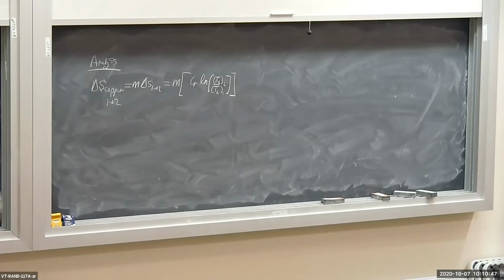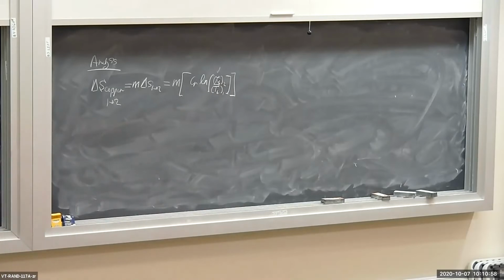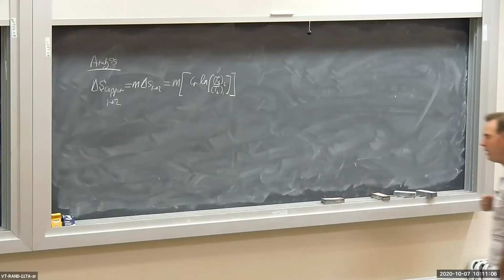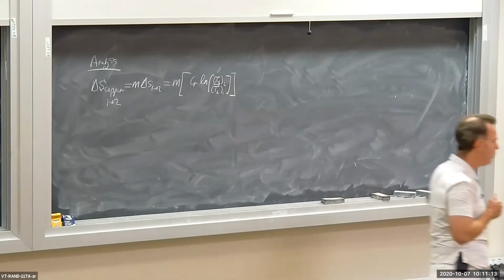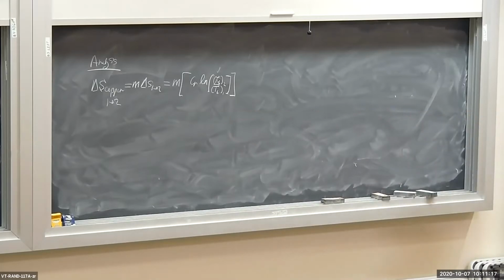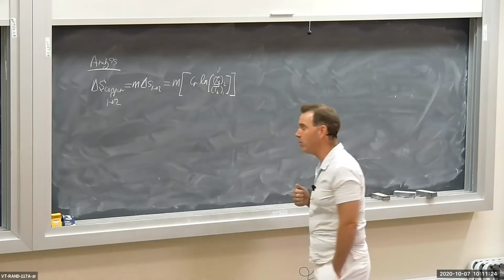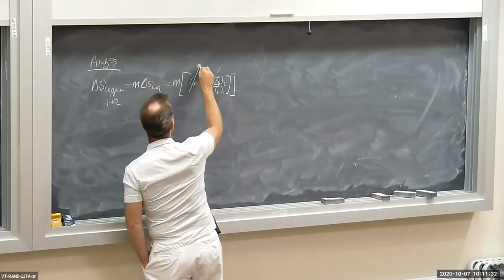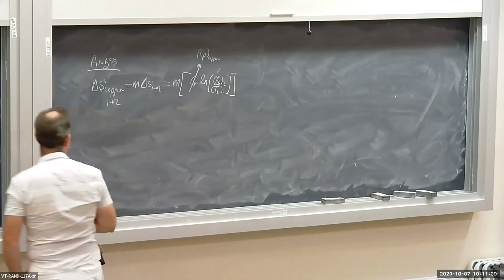Okay. Now, we've got the mass, we've got the initial and final temperatures. Check, check. Specific heat for the copper. Remember I was telling you last time, the reason for the difference between the value of Cp and Cv is the presence of boundary work. When you have heat capacity at constant volume, there's no boundary work over the process. And when you have specific heat at constant pressure, Cp, there is boundary work. Now, if we've got a solid or liquid or an incompressible, then Cp and Cv are the same value. So I can simply say this is Cp, for the copper. It can be Cp or Cv, all right? They're the same for a solid or a liquid.